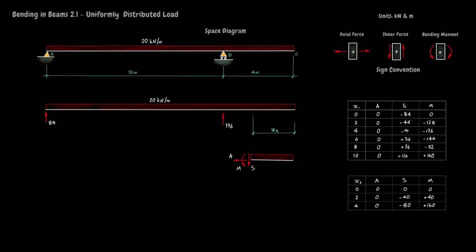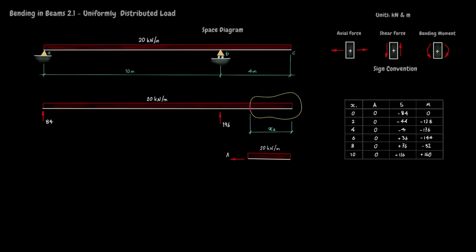Draw the free body diagram for everything inside the bubble we're using, remembering to include the unknown internal forces exposed by the cut. Now apply the equations of equilibrium to determine algebraic expressions for the unknown internal forces exposed by the cut.